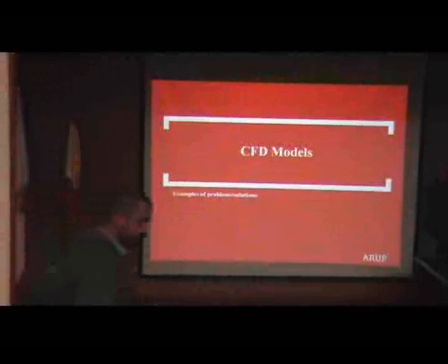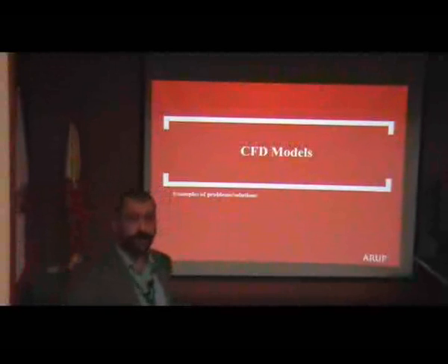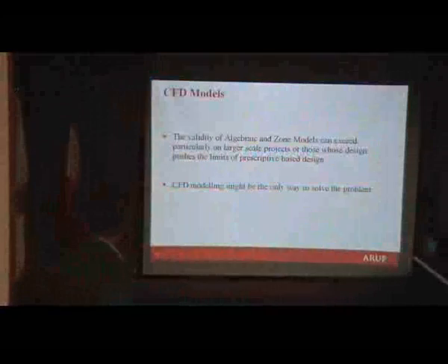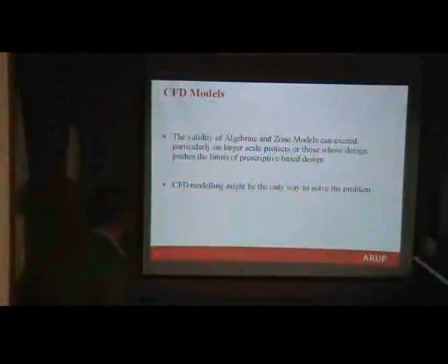And then there are CFD models. That is definitely the final step in complexity. So you need computational time, you need knowledge, probably more than what was used before. When do you use CFD models? Sometimes the validity of algebraic and zone models can be exceeded, particularly on large scale projects, or those whose design pushes the limits of prescriptive design. So sometimes CFD modeling can be the only way to solve the problem.